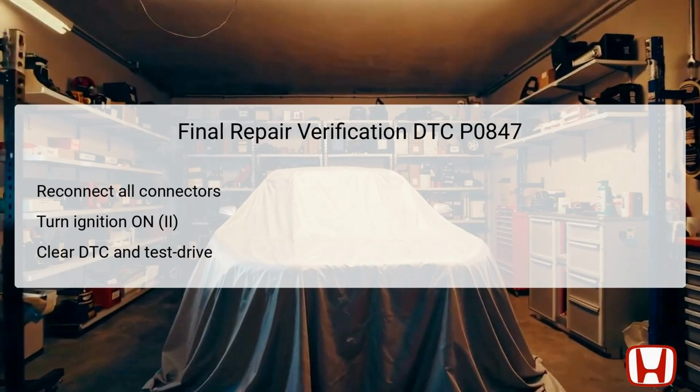Similar to earlier steps, the technician then needs to test drive the vehicle in both the 3rd and 4th gears for a duration of at least 2 seconds in each. Finally, checking the OBD status with the HDS is vital to see if DTC P0847 appears again as a passed, failed, or not completed result, confirming the effectiveness of the repairs performed.